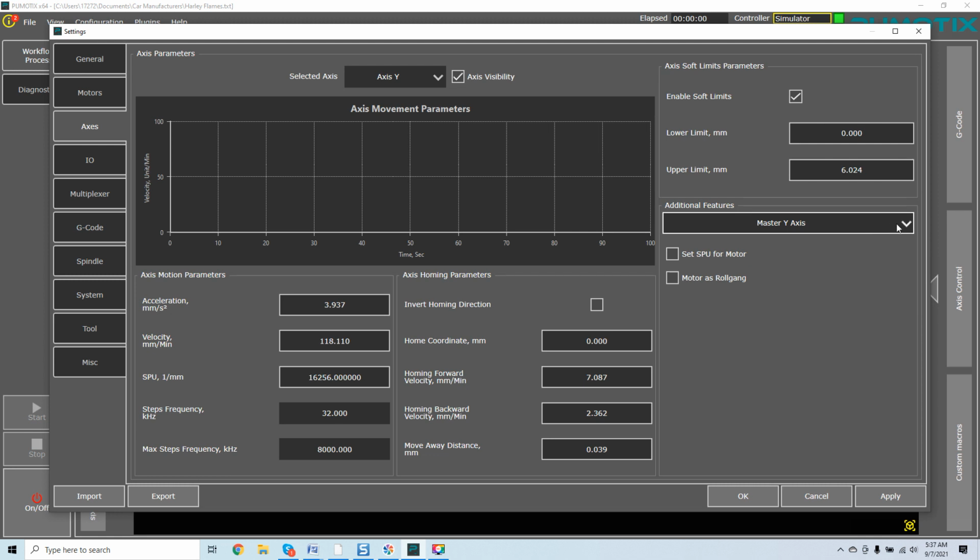Now this is super interesting to be able to do for whatever motor you're working with. So if you wanted to get a different step calculator done for a specific motor, you would be able to do that. Now that's only under certain instances. Now do not forget that this software does have a calibration setting for a slave configuration. It's the only software on the market that does that. So before you mess with this, I would certainly go through and do the calibration setting for your slave configuration on your Y-axis, and then you can do fine-tuning with this as well.